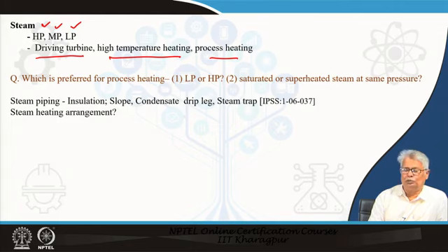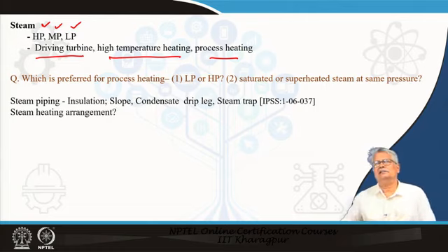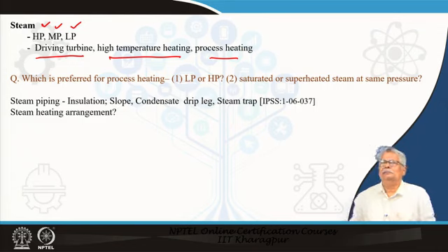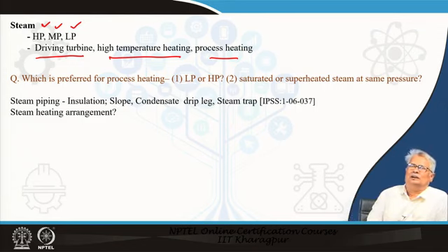It is also to be kept in mind that normally all these steams will be transported in a superheated state. Why superheated? Because in the pipes which carry these steam, there will be heat loss. If you supply it with a saturated steam right at the beginning, there will be condensation inside which you do not want. So, what is done typically is around say 30 to 50 or sometimes 70 degree superheat is present in the upstream of these steam headers.